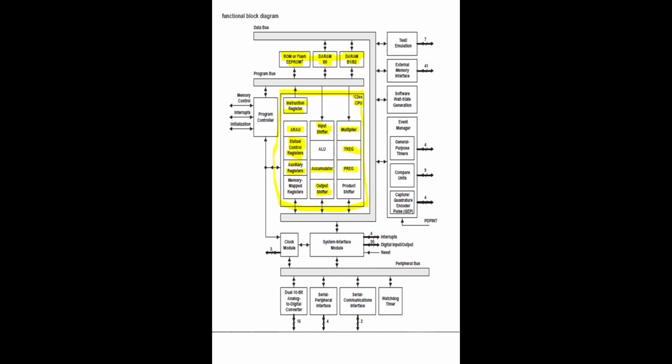Before the product register output, that means the multiplier output, reaches the central ALU, if you wanted to shift that answer also, then I'll be using the product shifter. This product shifter is purposely and specially given for multiplier output shifting. This is not like your output shifting. That output shifting is for arithmetic operations other than multiplication. So this product shifter will shift only the product output of the multiplier.